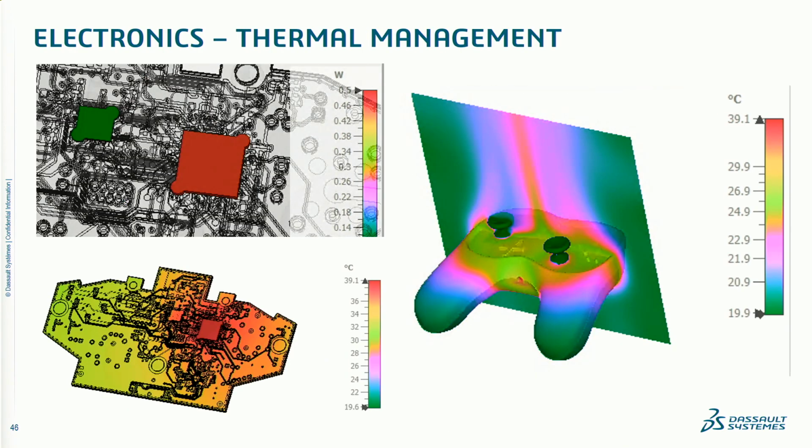We're okay. Now, I mentioned thermal as well. Once we go in and run the power integrity study on this, we have a great idea of the losses all over that board. We can directly, in the same package, run a thermal study on that. And again, built-in CFD solving specific to e-cooling, and we can go in and get very accurate ideas of what the temperatures are, not just in the board, but also in the mechanical components, also in the airflow that's moving around it, etc.